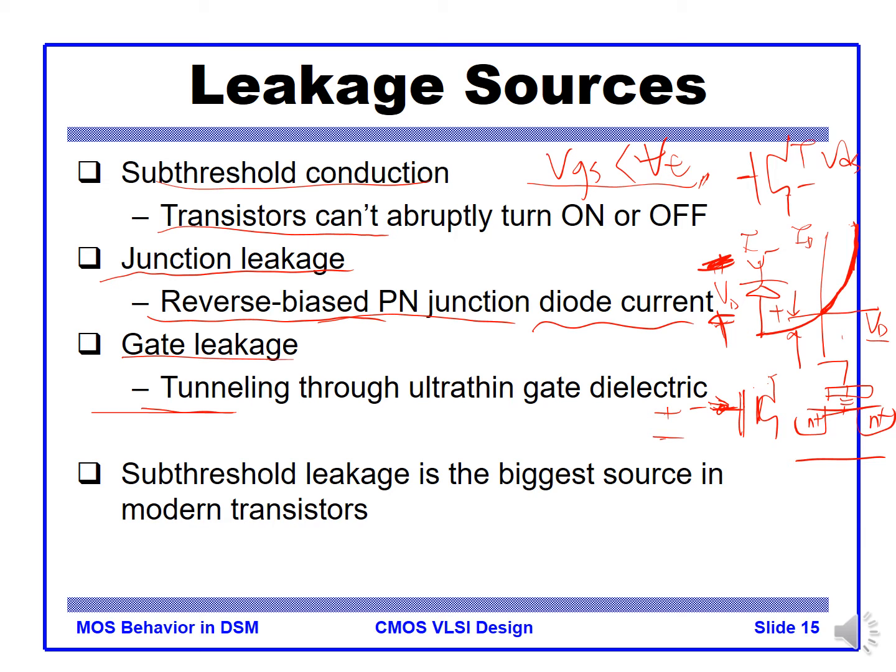They're supposed to have zero DC current, but because of the tunneling effect, a very slight amount of current flows between gate and surface. This happens because we are dealing with a very thin gate dielectric. So a fine process will always have non-zero current flow from the gate to the channel.